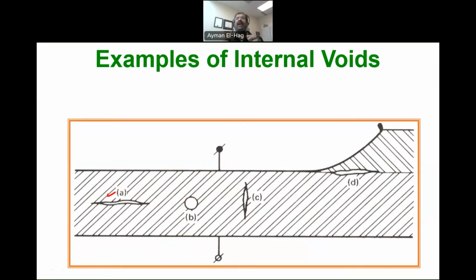These defects are inside the bulk of the material. And this bulk material could be cable, XLPE, polymer, any type of outdoor insulator, any type of dielectric material, or a void inside the oil in the transformer tank.